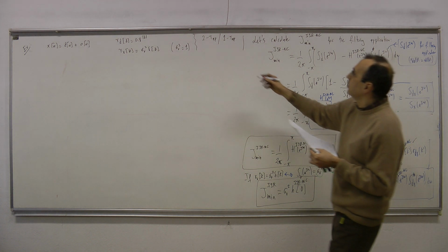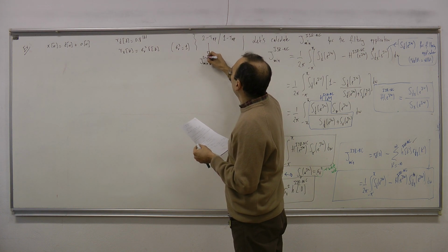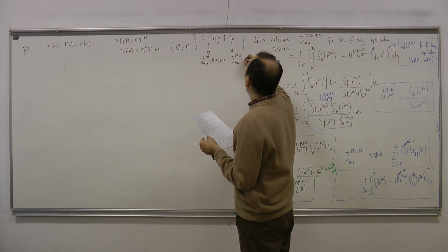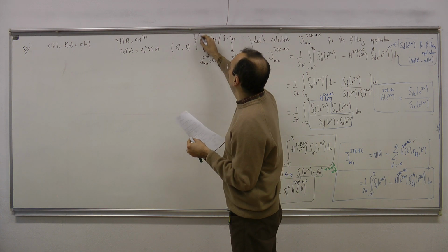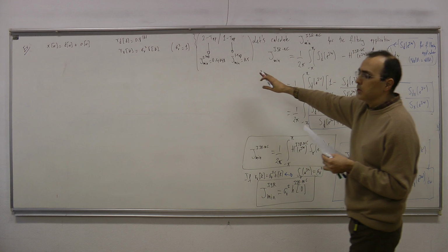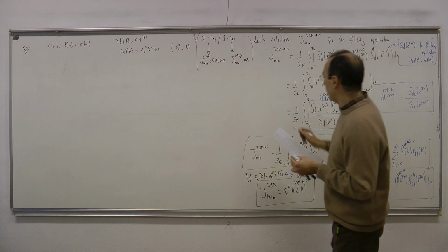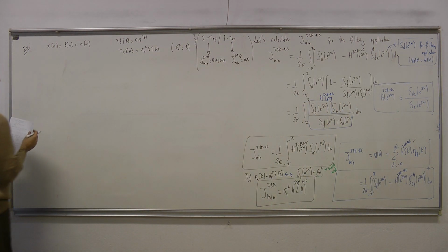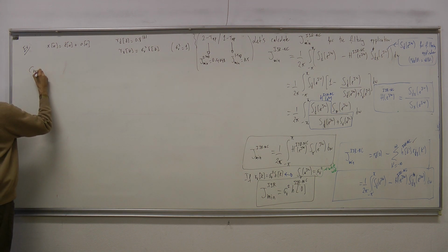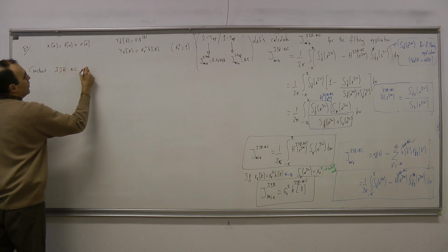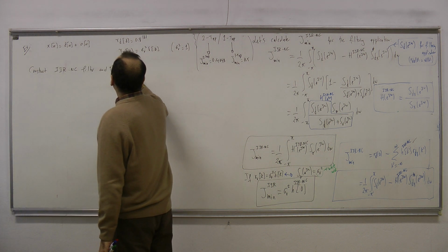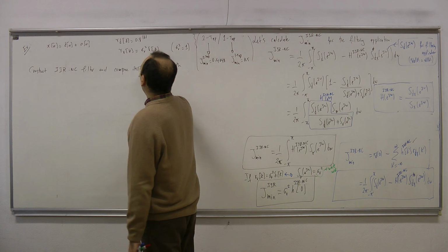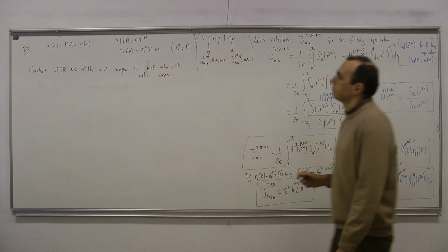For the two-tap result, maybe you can remember from the earlier lecture, J minimum two-tap value was 0.4048. J minimum one-tap value, one-tap FIR filter, was 0.5. We had some earlier results like that from previous lectures. And this was a topic that we have discussed, the maximum SNR filter, whether this MMSE minimizing filter is a maximum SNR filter or not. This was the same example. Now the goal is constructing this IIR non-causal filter and comparing its MSE value with earlier cases.